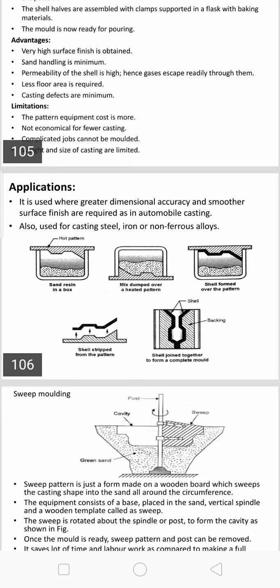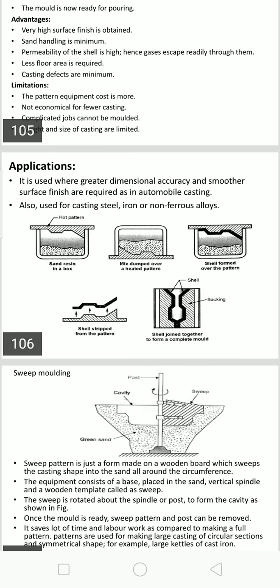The shell is then stripped from the pattern plate by means of ejector pins, or by operating the ejector pin. That is another step. Similarly, another half of the shell we have to prepare. These prepared shells are to be assembled again.